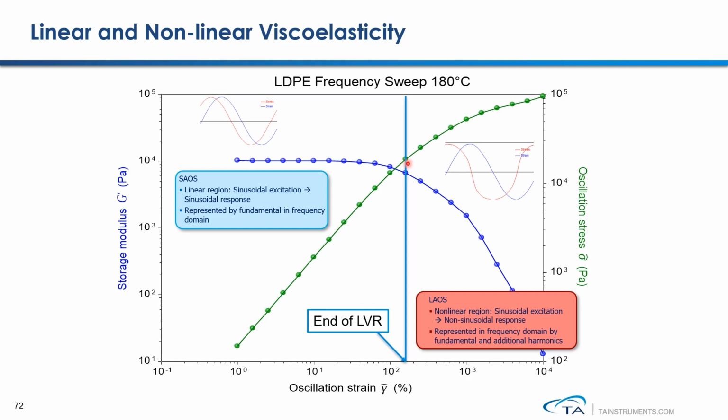As you gradually increase your measurement strain up to a certain critical point, stress and strain start not following the straight-line relationship. The stress curve starts to deviate from the straight line. In the meantime, the sample modulus starts to show a decrease. As you get further and further outside this critical point, as the strain is further increasing,